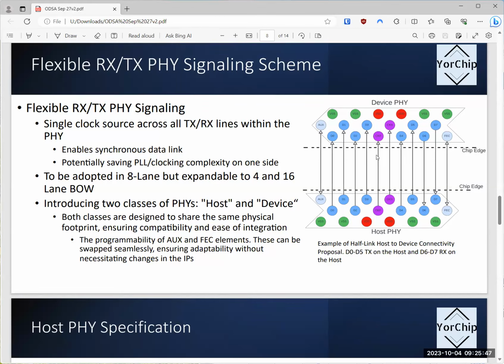So basically, how should I say this? If each, so okay, I shouldn't have said it the way I did. If each clock is still technically able to be bidirectional, it's just that if you want a PHY to be able to both transmit and receive, one of the clock pairs needs to be a transmit and one of the clock pairs needs to be a receive. I think you're fine. In other words, I think you can avoid the particular issue you're worried about as long as you have the statically configurable direction of the clocks, but you can still make it so there is actually a forwarded transmit clock and a forwarded receive clock. Do you see what I mean?